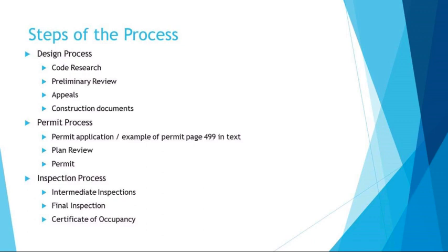A certificate of completion is used when the structure or systems within a space or building are complete. The certificate is usually necessary to connect to local utilities, especially in new construction. A certificate of occupancy must be issued to allow the tenant to occupy the space or building. It is issued after the final inspection has been completed, and sometimes it's called C of O, and the person obtaining the building permit typically requests the C of O from the code official. This is usually the contractor.